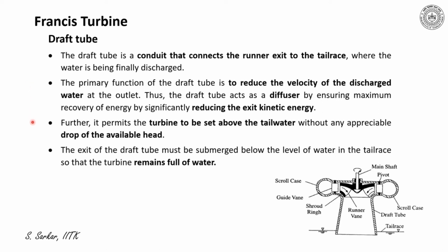Further, it permits the turbine to be installed above the tail race without any significant drop of available head. Please note that this is an important point, that the draft tube permits the turbine to be installed above the tail water without any significant drop of available head. This I will explain later.